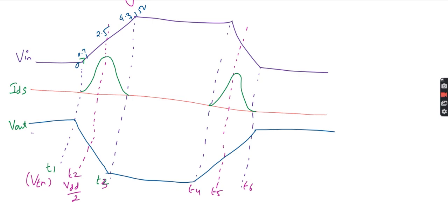After that what will happen? It gets reduced, right? It's a CMOS inverter. You might have studied the VI characteristics curve and all, right? So the same thing, whatever we did here, the same symmetry will be there even here also. What is T3? As I mentioned here, T3 is nothing but VDD minus VTP. VDD minus VTP, right?